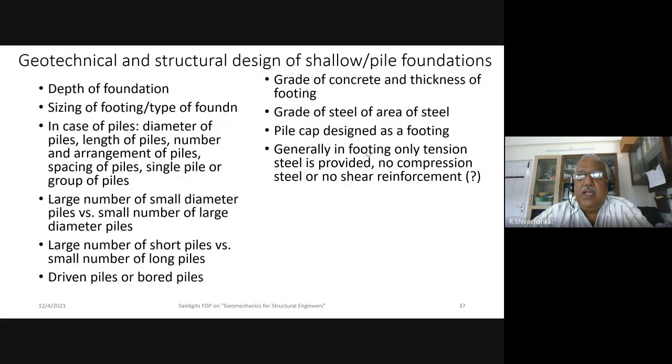In design offices we have a structural division and then a geotechnical division. The structural engineer, I'm not making any difference, but the person doing the structural design designs the structure, whatever the number of stories, by assuming a fixed base, right? He's not worried about the type of foundation and the type of soil. So he does the structural analysis and then transfers the loads in the lowermost columns, the loads and moments, structural loads and all that.